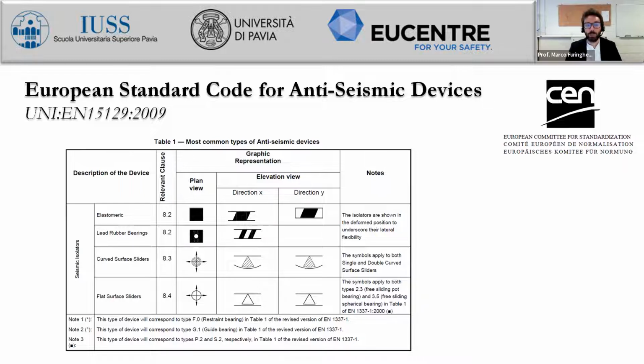So in order to have our performance point, we will call it performance point. But then I have just 10 isolators, and I have to cover 25 bearings. So I need some other devices, and those devices will be flat sliders. And the flat sliders, in order not to mismatch the initial results of design, will have a very low friction coefficient.